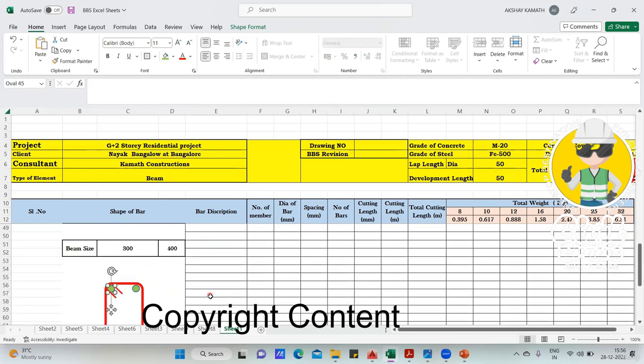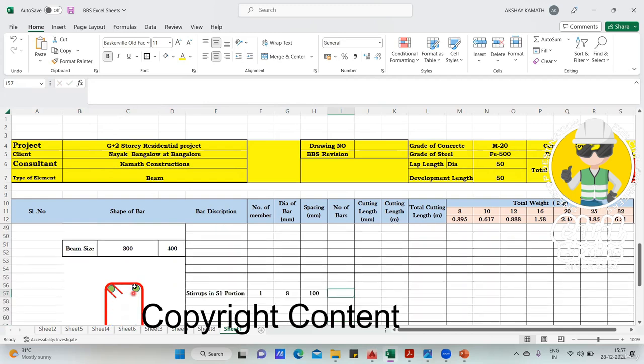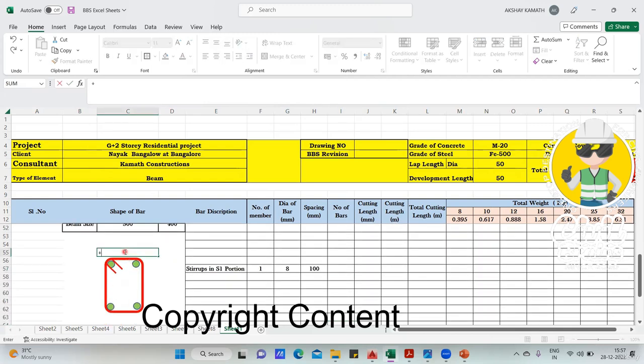First we'll write here stirrup, in which portion? S1 portion. Okay, fine. Number of member it is 1. Dia it is 8 mm dia. And this spacing is 100, I think. Okay, so then just come here, select this portion, plus.